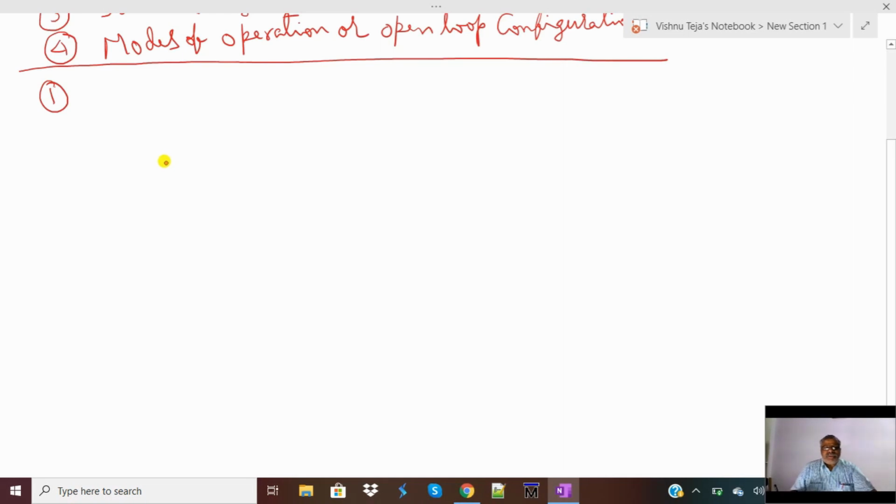The internal circuit of an operational amplifier is very complex, consisting of more than 50 transistors interconnected with each other. So, the equivalent internal circuit, or simply the AC equivalent circuit of an operational amplifier, can be represented with 3 simple components: Ri, R0, and a Thevenin's voltage source.